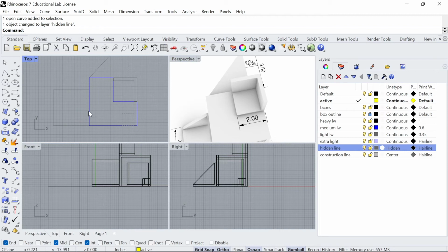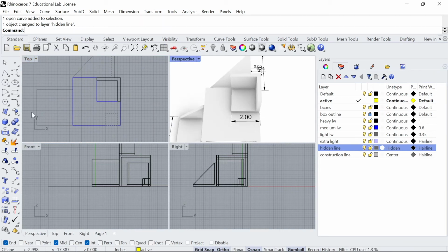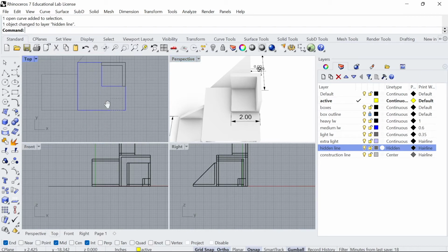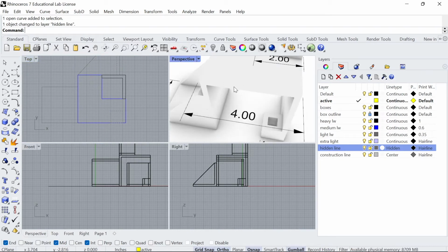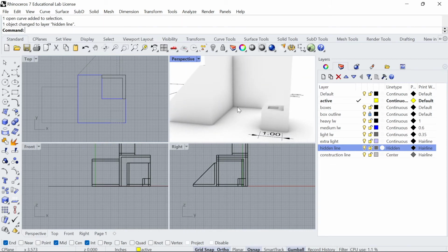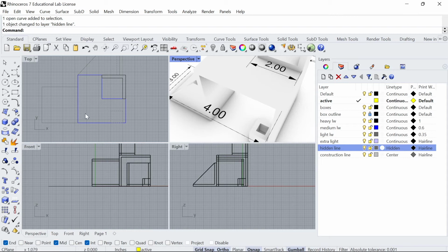So the next thing we want to do is draw a little bit more hidden lines that we can't see, and then finally get to this last cube, which is probably the more difficult one in terms of representation because you're seeing that angle. Okay, but first we know that there's a few hidden lines. We know that this box, the 4-inch box, has a thickness on both sides and on the back end right here. It has an exposed face up front. So we have to consider that when we're drawing this.